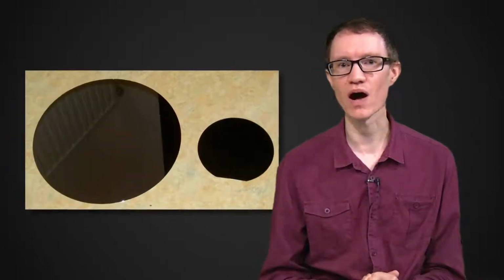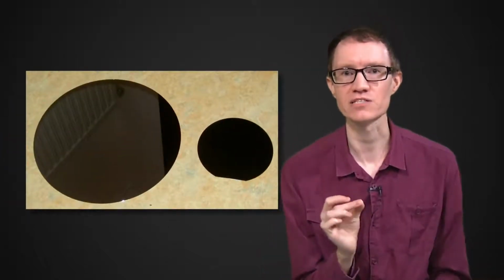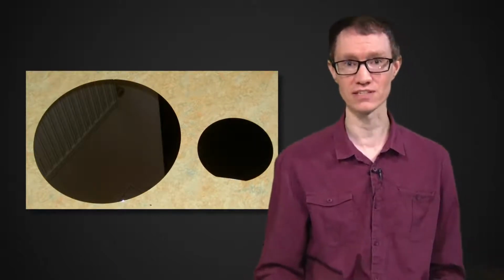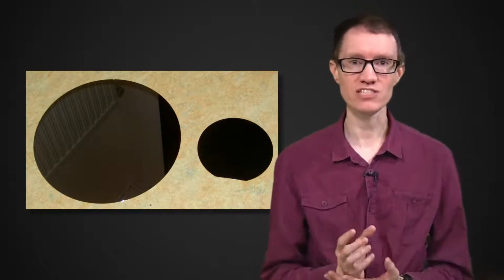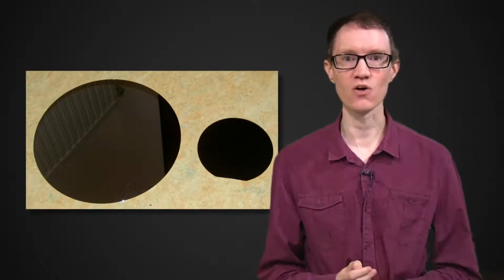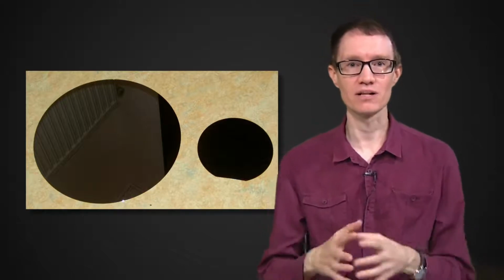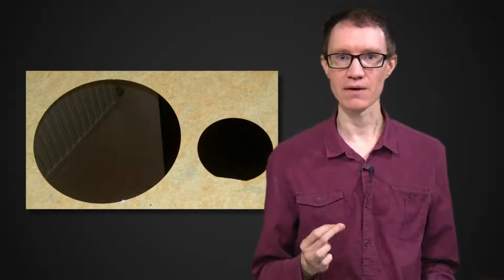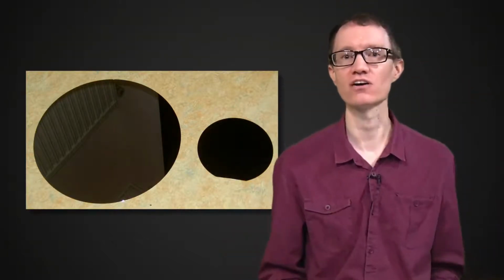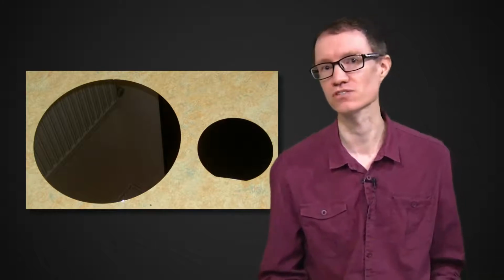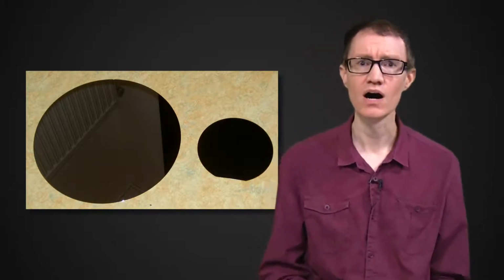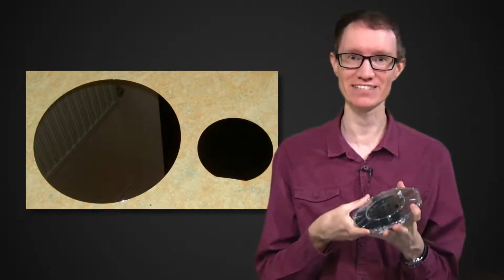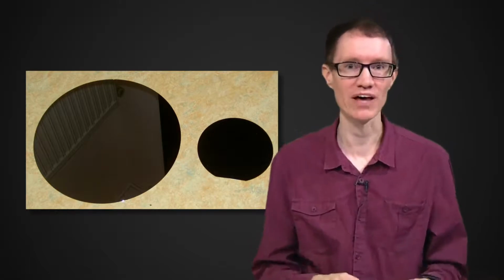And one of the reasons why the electronics industry has progressed so rapidly in the last few decades is because of the technology involved to grow these silicon wafers. Wafers are just slices of crystal sections called boules, and they're practically grown in a big vat from a very small seed silicon crystal. They pull out the material from the melt as it hardens, and then they slice up the resulting crystal into wafers. So what I'm holding in my hand right now is just a cross-section of a giant silicon single crystal that's been pulled out of a melt.